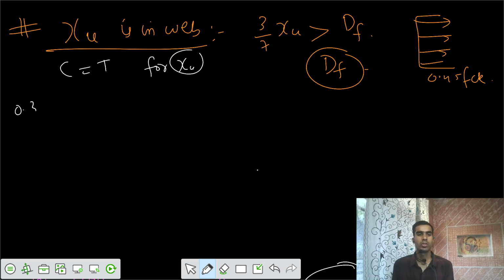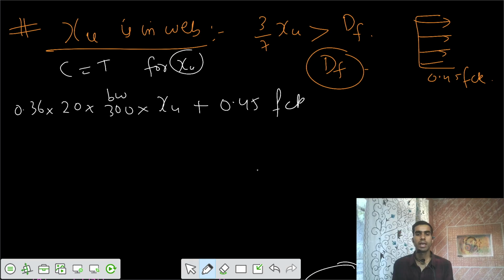So I would say 0.36 fck bw xu, bw was 300, plus C1 plus C2. C2 force is 0.45 fck, and the (bf minus bw), and we have that Df was 100.